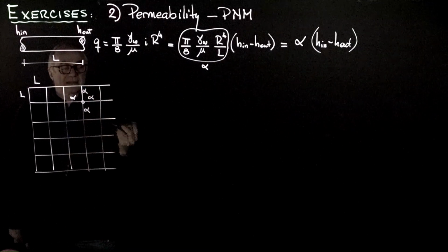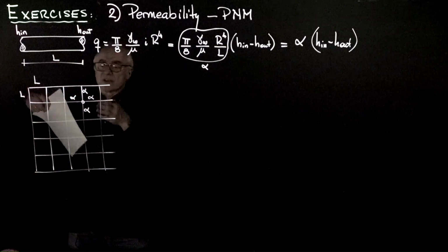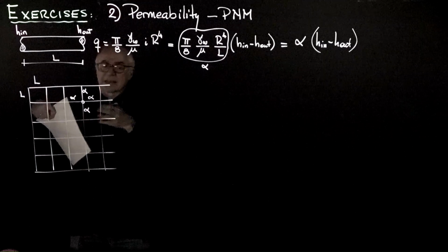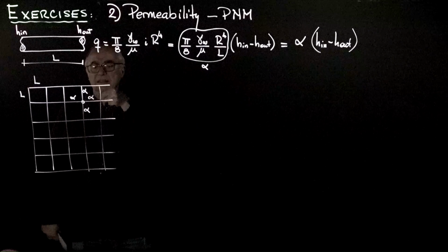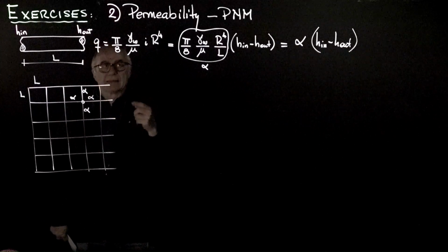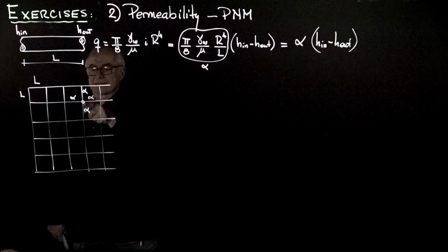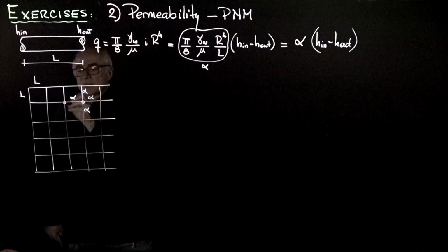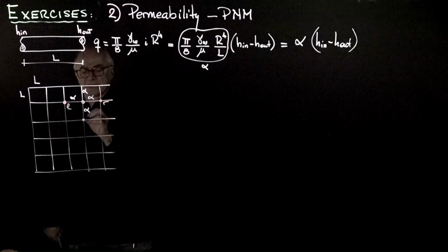And now that means something very valuable, because all the fluid that converges to that node must come out of that node. And so we can add all the Q ins and the Q outs. And the only thing that we need to do is to solve for the total head at the center.